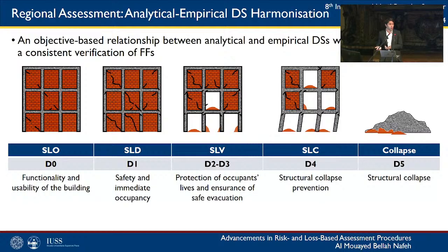But other components, such as damage accumulation, are even a significant component to this discrepancy, which was highlighted by the initial 2 damage states, because for buildings that have not suffered damage limitations, if we compare analytical with empirical models, they should match more or less. It's not until we push the building enough into the nonlinear range of response that this damage accumulation component will be a considerable factor in how we relate empirical and analytical fragility functions. To answer your questions, I believe both factors play a solid role in this discrepancy. Thank you.